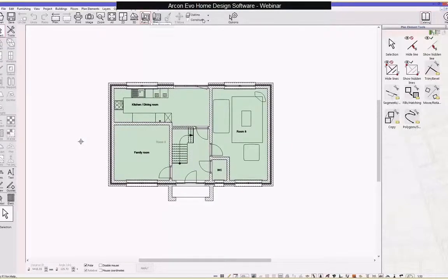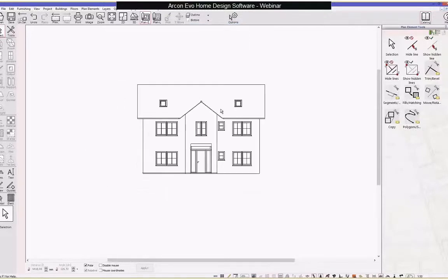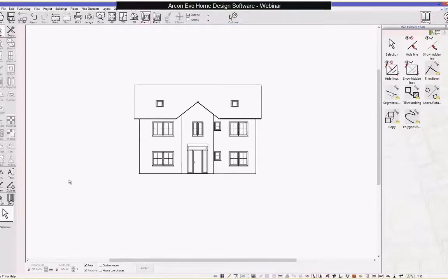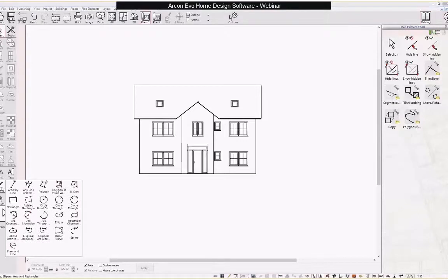So I'm starting to build up. If I click on this drop down list here, you can start to see a number of views being built up. Once you're happy with the number of views you've got, I can then click on this plan layout mode. Actually, sorry, one thing I didn't mention: if I go back to the bottom one here, the elevation, as I mentioned earlier, you've got 2D drawing tools here as well, so you can apply your own detail to the actual elevation view as well.